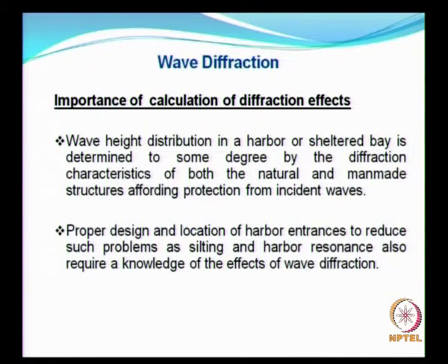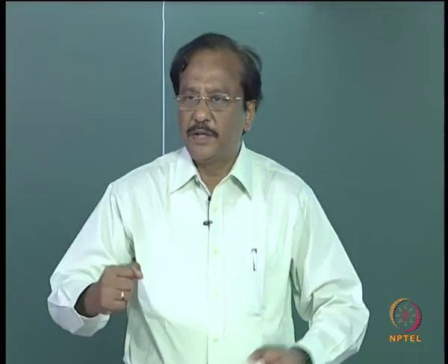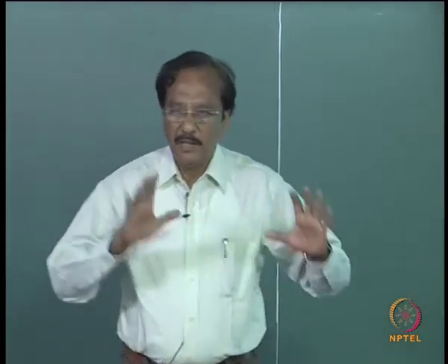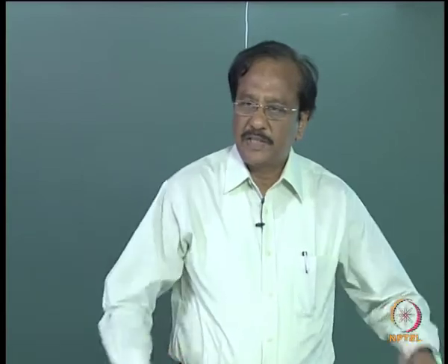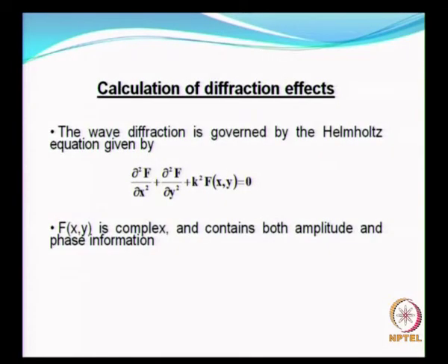So when you plan for a harbor, one thing you normally do is consider the predominant wave direction, and you consider more or less the long period waves in that area. You try to align your breakwater and also fix the gap between the breakwaters in such a way that you have minimum disturbance after the construction of breakwaters. So diffraction calculation is not so easy compared to refraction, which we have seen earlier.